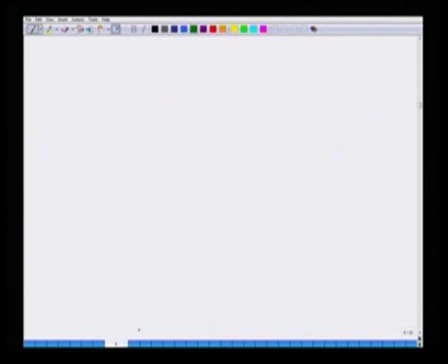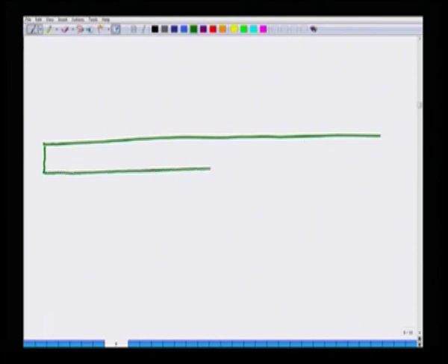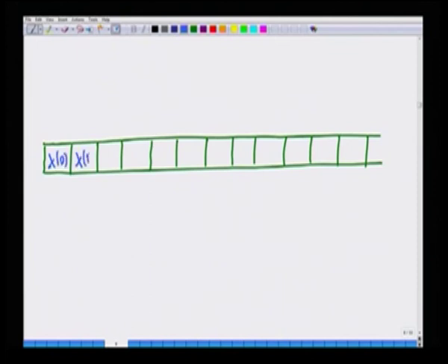Another simple way is of course to simply do a zero padding operation. So, I have again 12 subcarriers. What I can do here is load them onto the first 4 subcarriers and leave the rest of them 0.